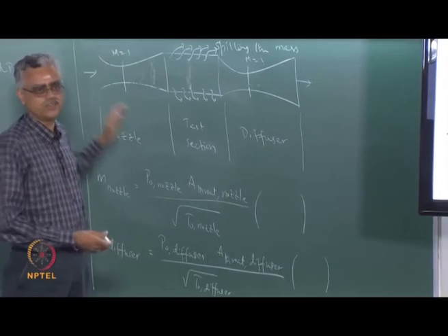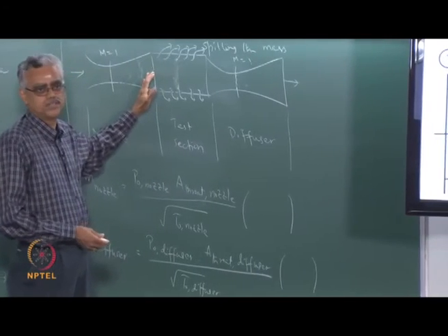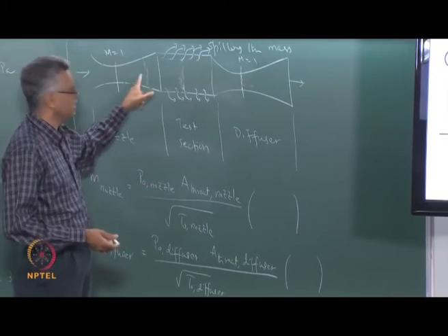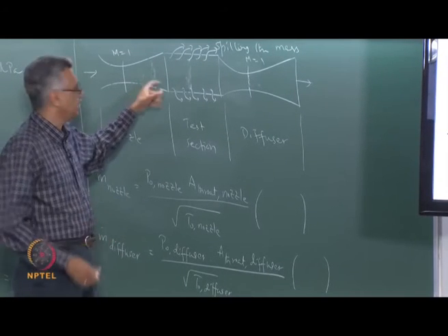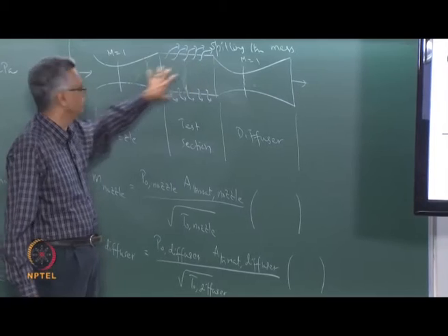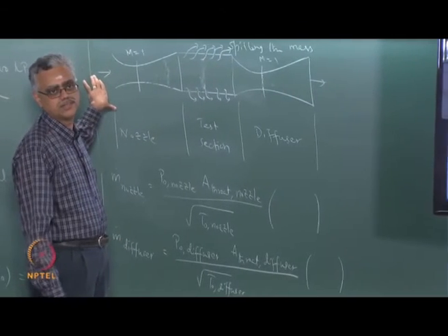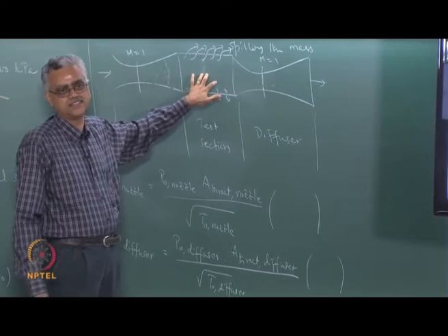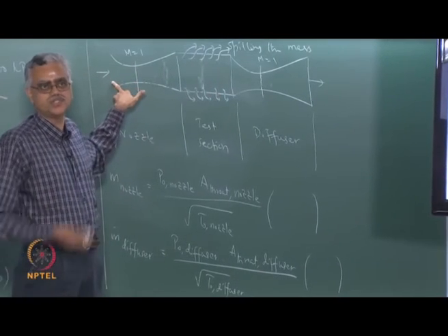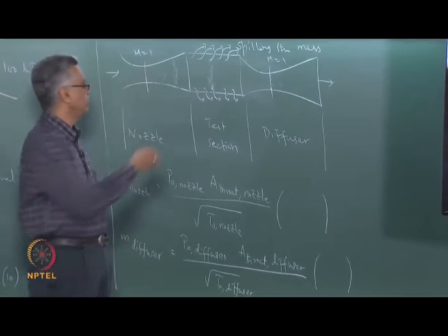So the brute force way of pushing the shock down here will not work because of the mismatch and loss of stagnation pressure across the normal shock. Okay? So when you do that, what will happen is this increase in pressure will tend to push the shock backwards. Then you establish shock free flow, but subsonic flow in the test section. Because this stagnation pressure is already high, again it will trigger a normal shock.